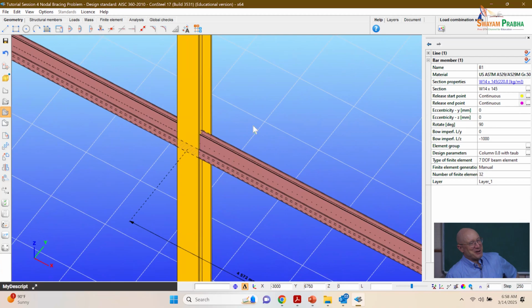What I call J is KT? Yes, yes. All right. So KT will be equal to KY in this particular case, the usual case that the other day we were talking about. KT is basically the sum of bt cubed over 3 of all the plate elements, right? I was talking about the effective length in torsion. Oh, okay. And the effective length in the minor axis, we call KZ, right? Yeah.